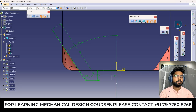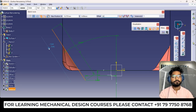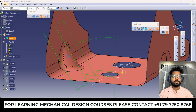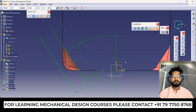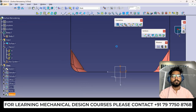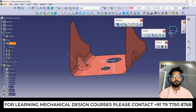So if I use the offset command, select this line, and keep the offset distance 3.6, that is the radius, right? And if I make this normal, now this line will turn into construction, and this is the center line I am getting. Okay, exit. So we are trying to create one small pipe shape here, because this is a pipe type of shape.